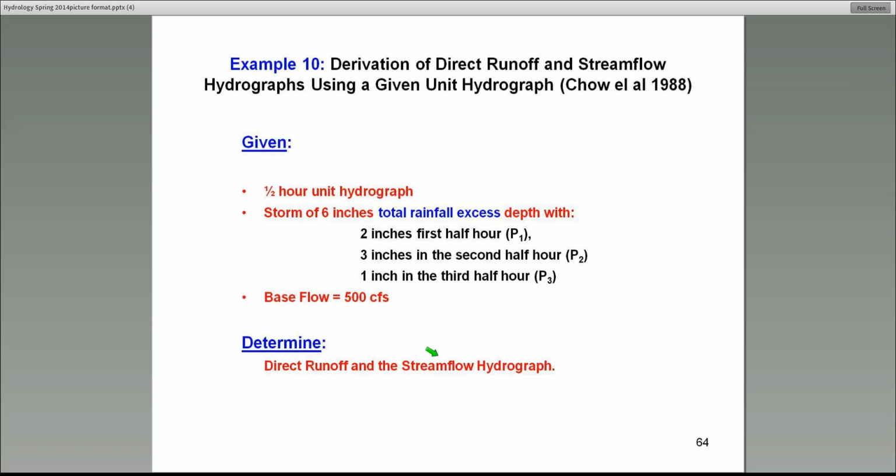For the streamflow hydrograph, which I'm also asking here, you basically have to add the base flow back again. There is a question here before I show this example. For Tc of 1.5 hours, is Q 300? Well, somebody reads it as 300. I think if you read it carefully, it probably should come to 285, okay? This is in the SCS unit peak discharge method.